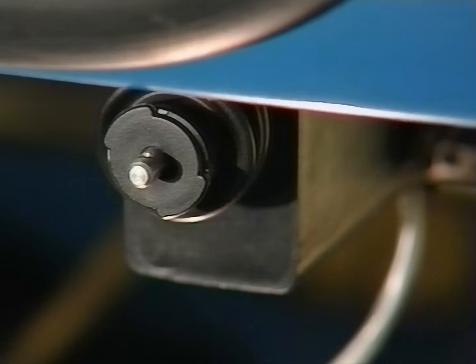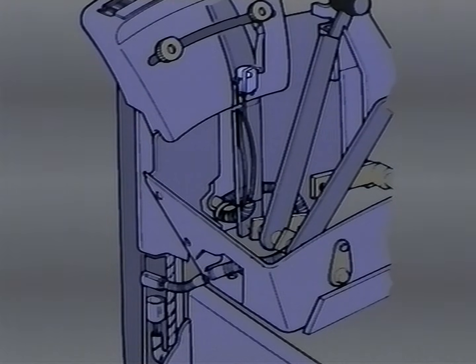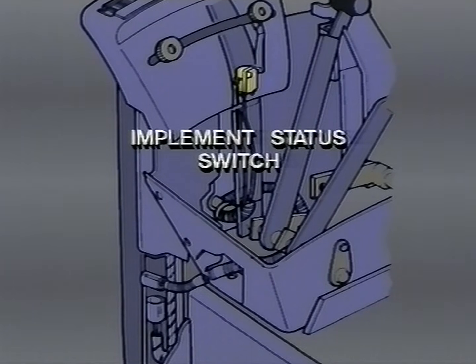For obtaining information about whether an implement is raised or lowered, as well as for establishing beginning and end points for area calculations, the TPM relies on an implement status switch. On TW tractors, the switch operates by a pull chain attached to the three-point hitch lift arms. This type of switch is easily remounted on a trailing implement. On Series 10, four-cylinder tractors, and on the 8210, the implement status switch is mounted on the lift control lever. It uses a plunger to open and close the contacts in a micro switch.